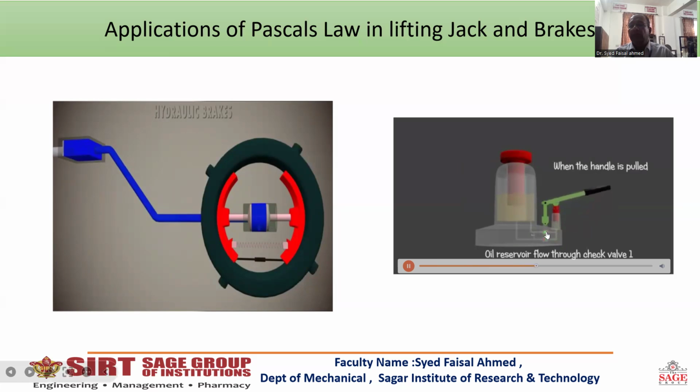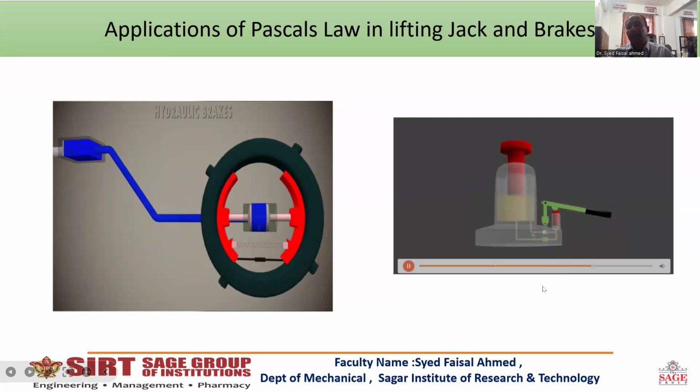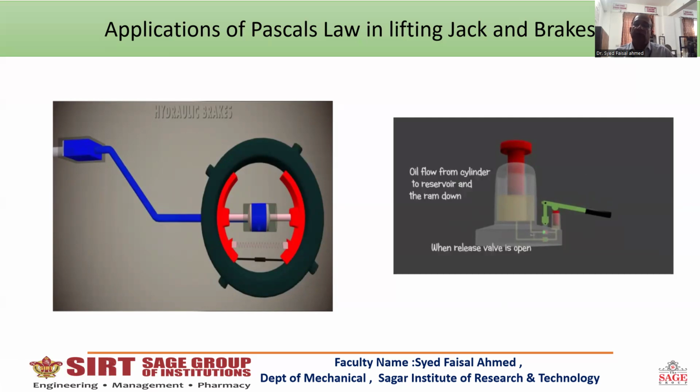Here, the valve is open and then fluid enters it. Oil enters the bigger cylinder, and the force and the load is lifted. This is how a hydraulic jack works. It is based on a common example.